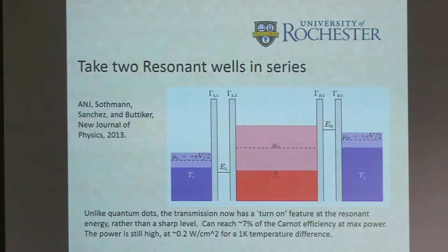The idea, something again we published with Rafa and Bjorn, is we have the same kind of geometry I talked about before, but instead of having a 0-dimensional device, you have this planar structure. And you put the lowest level, again, somehow below the Fermi energy here and above the Fermi energy there, and you can play the same kinds of games. So it turns out it's not as efficient as the quantum dot resonant tunneling geometry, but you can produce a lot more power, and it's scalable, right?